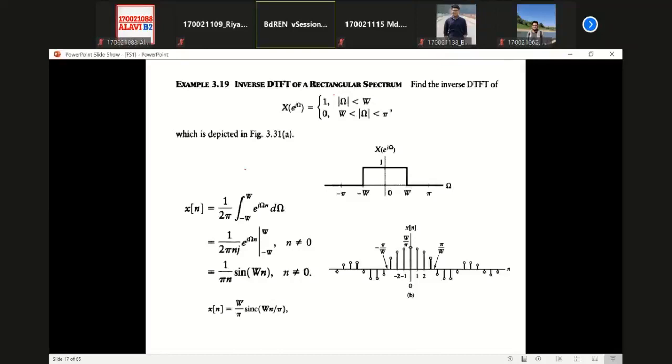Okay. One thing is that for an aperiodic signal, we have to use Fourier transform, okay? Your Fourier transform has a forward transformation and an inverse transformation. Inverse transformation will bring back your signal into the time domain, and your forward transformation will transfer your signal to the frequency domain. Your Fourier transform of an aperiodic discrete-time signal is a continuous function of capital omega, and it is periodic. We need only one period of your Fourier transform to reconstruct our signal.